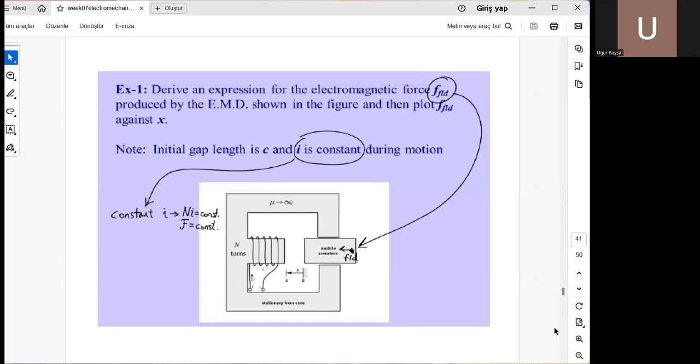Equations as well as torque will be handled. So for the linear case, any linear moment, linear forces, plungers, etc., we may use these two alternative methods. If we can calculate the co-energy, then take the derivative with respect to x. If we can calculate the energy, again taking the derivative with respect to x and a minus sign in front, it gives the same field force as well.